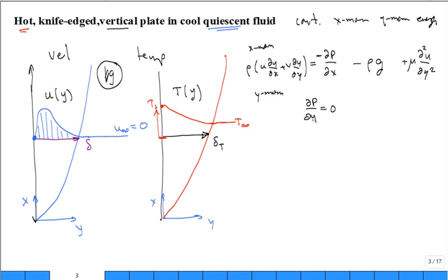If the pressure is only a function of x, then what we find is that the change in the pressure with respect to x is really the change in the pressure far away with respect to x, and it's just minus rho infinity g. It's hydrostatic pressure far away. It's like a column of fluid far away, and we just have hydrostatic pressure. And the pressure way out there just penetrates into the boundary layer. It's a long discussion. Maybe I'll let you think about it some more. But we can put this in here.